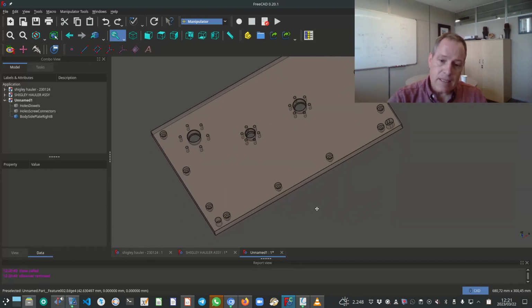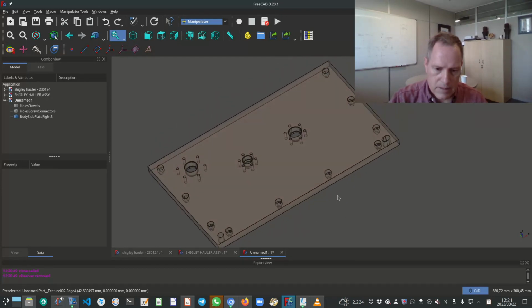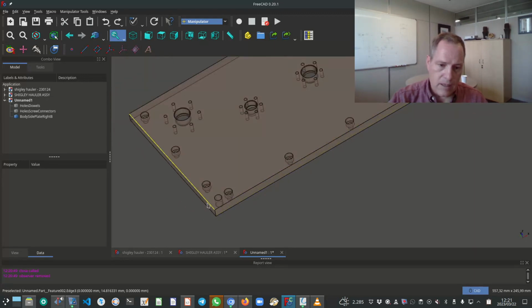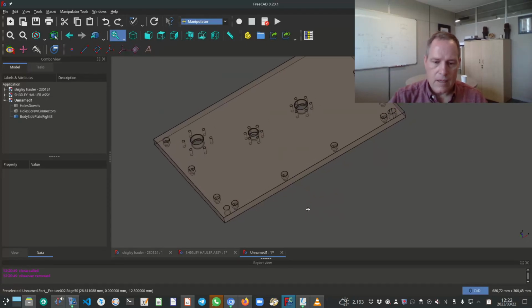Select the largest surface that you will use as a datum as the primary datum, and a smaller surface as a secondary datum. So I hope it is clear for you that you can select, for example, this face as the primary and this face as the secondary. Then you will have basic or box dimensions from those 2 faces, and you can control the position of that hole very accurately.